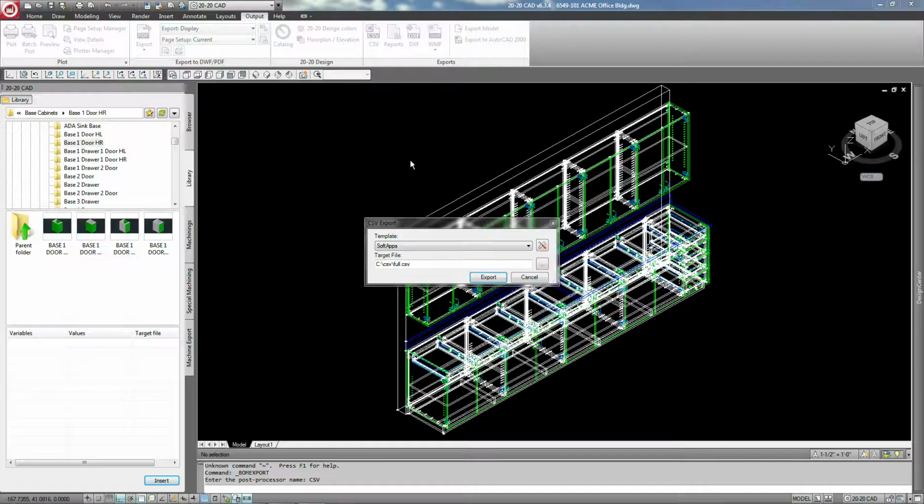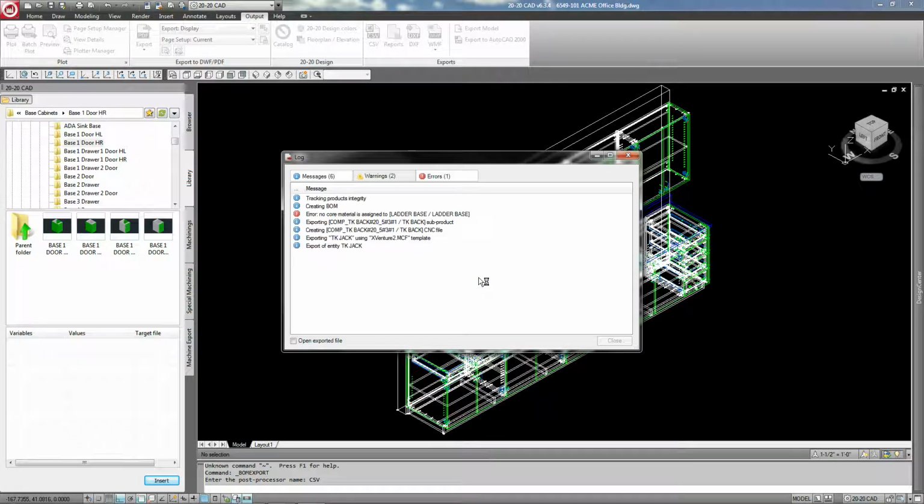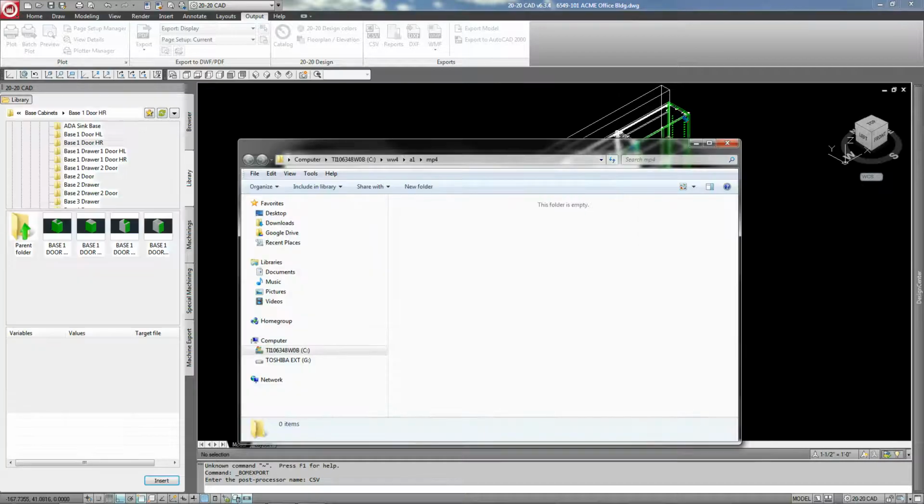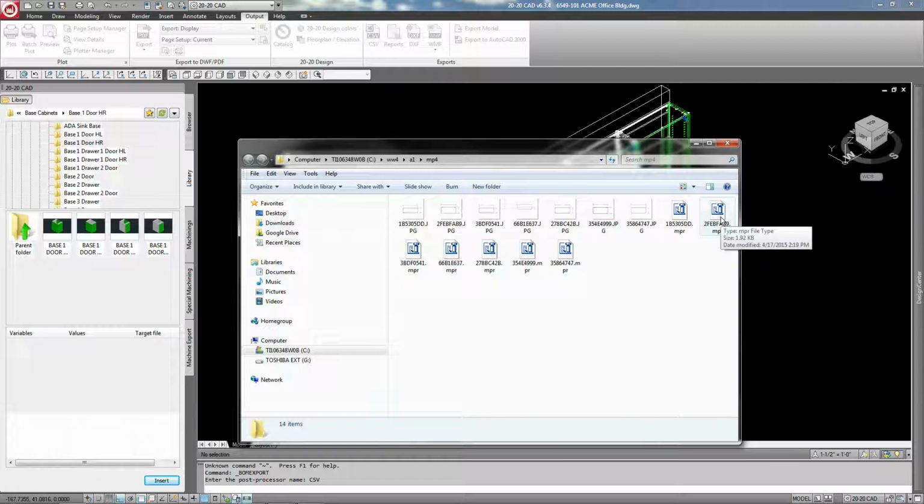So it's going to automatically save the drawing and refresh all the parametrics. The CSV file will also generate all the MPR files required for the project, and it'll only generate MPR files based on whether there's machining associated with a part in a piece. It also will generate a JPEG file, which will indicate its size and its 0, 0 location on the point-to-point.